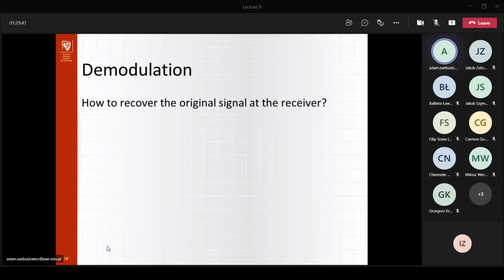This has to do with the fact that a typical diode is a PN junction, and you might have problems with capacitance at the diode. So in general, what you are suggesting would work up to a certain frequency. Above a certain frequency, there are technological constraints, simply because the rectifier diode is not simple enough to extract all the information.